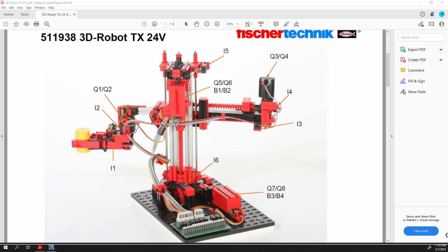If that counter block needs to see a low signal to a high signal for it to count up one, that means we have to take two loops, right? Because we have to go from a low loop, next loop has to be high, loop again has to be low, loop again has to be high. So at our best, with a normal counter in our code, you can count 500 times per second.